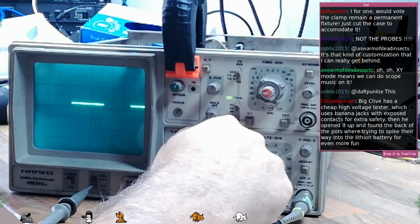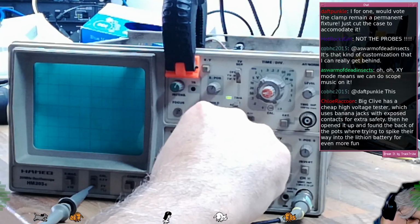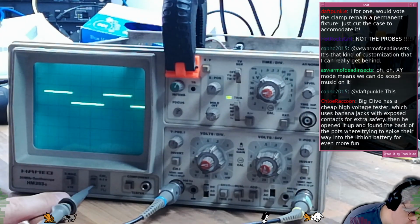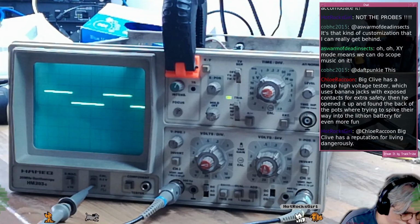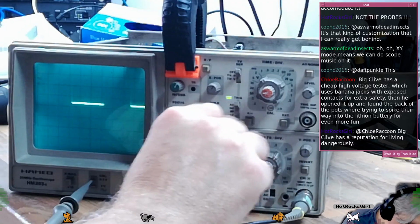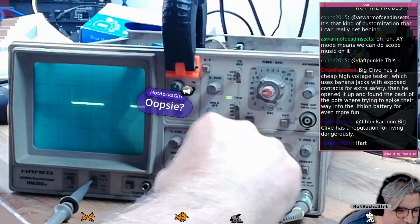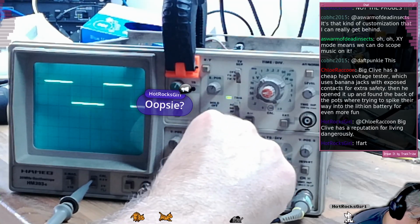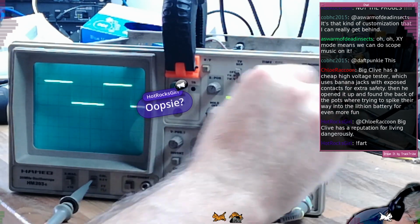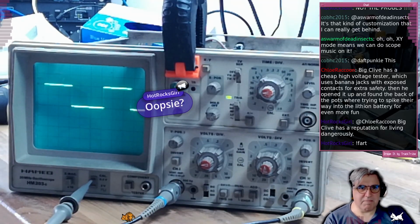Now that goes the full width. So that is 0.2 volts per division, and this is supposed to be a 2 volt peak to peak signal. Maybe it isn't. Maybe I've got this connector in the front here in backwards. Oops. Okay, so 1 volt per division. No, and we're seeing a 2 volt signal. There we go. Yeah, my calibration connector is backwards.